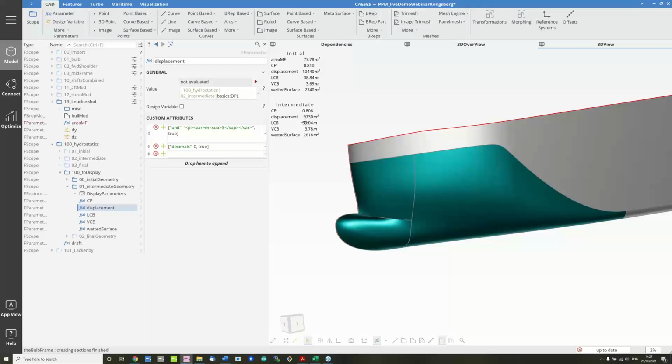And what I can do, and I think this is to be considered the holy grail of partial parametrics for naval architects, is using a shift function to bring these characteristics back to where I want them. We call this a generalized Lackenby. And this transformation allows us to actually set those measures to exactly where I want them to be. So what I've done here, in this case, I've set up a Lackenby that is set up such that it would bring back the hydrostatics to what they were initially.